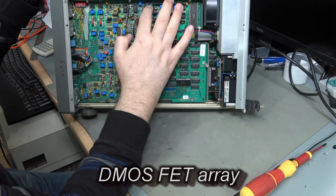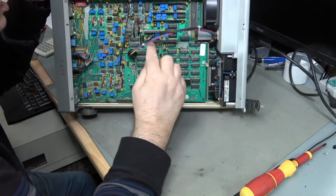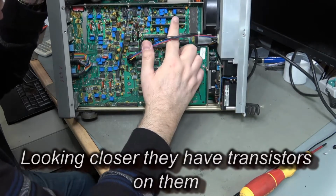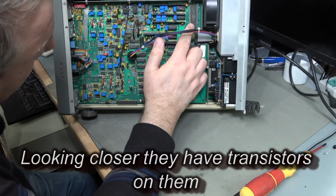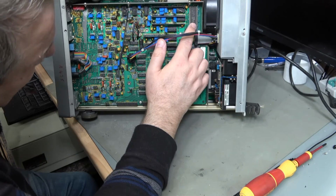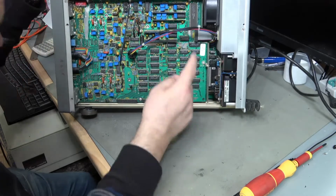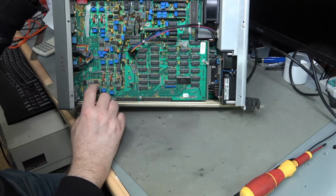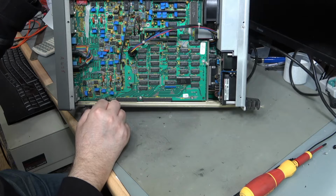SD5000N. That's a bit 74LS logic. We've got some interesting networks up here. I'm assuming these are divider networks. And up here we've got Nicolet data assembly. More 74 logic. Some are socketed, some are not. Generally speaking, most of it's bog standard logic. Up here it looks like we've got a few op amps, CA3140. Seems to be the device of choice.